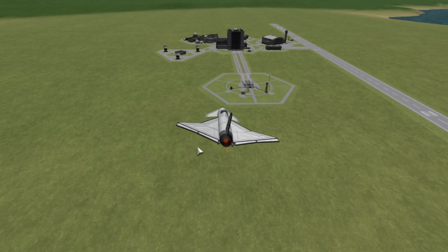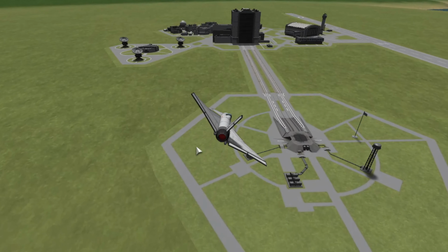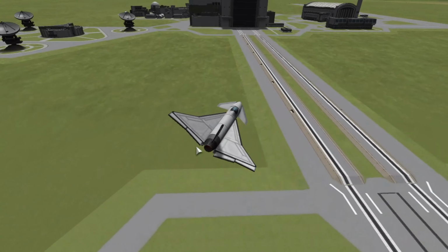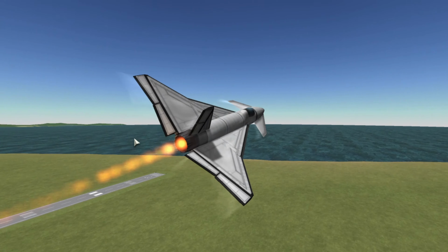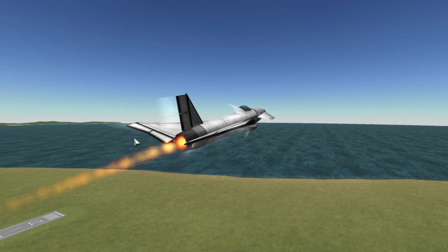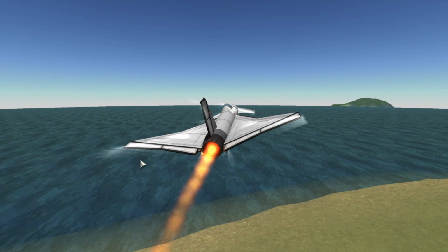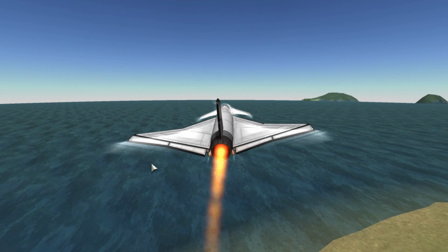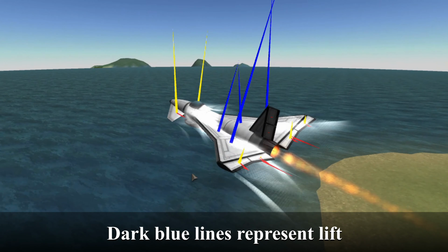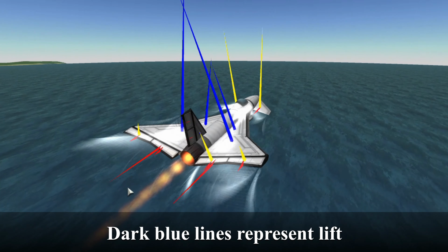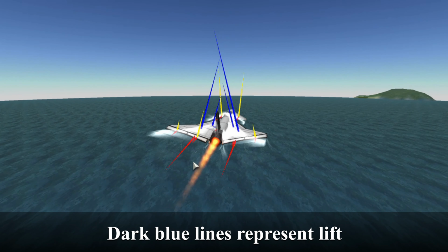It does this because the plane is now rolled slightly over. Now that the plane is rolled, its wings are creating lift that isn't vertical, which means that this plane is now going in the direction of the side of the plane that has the lower wing, which means that the lower wing is now deflecting air from in front of it and to the side of it, which means that it's deflecting more air and is therefore producing more lift than the other wing, and the plane starts to roll back to normal.